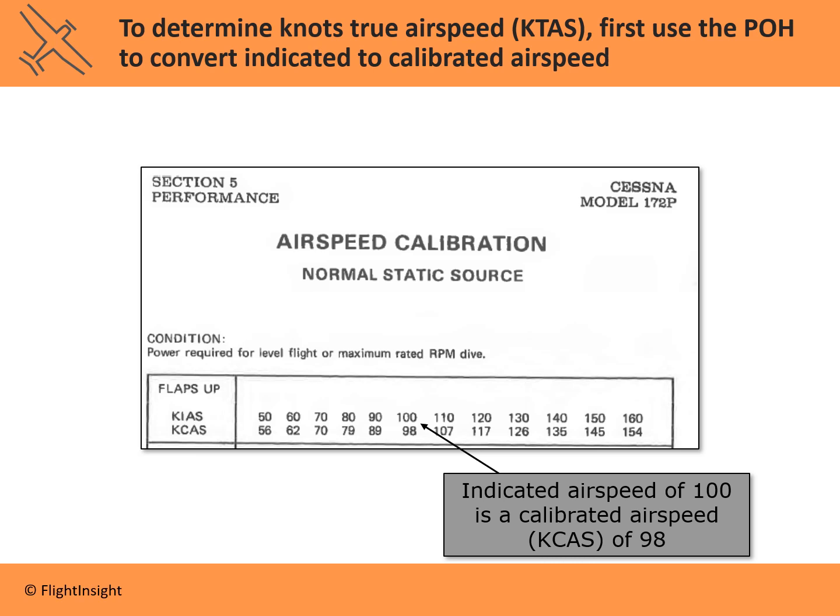Now, in order to determine our true airspeed, we're going to have to start with what we know inside the cockpit. So let's say we know that when we're up at altitude, the aircraft is going to be doing a certain speed indicated on the airspeed indicator. Now, we can know that just from experience, or we could know it from looking at the performance tables in Section 5 of the POH.